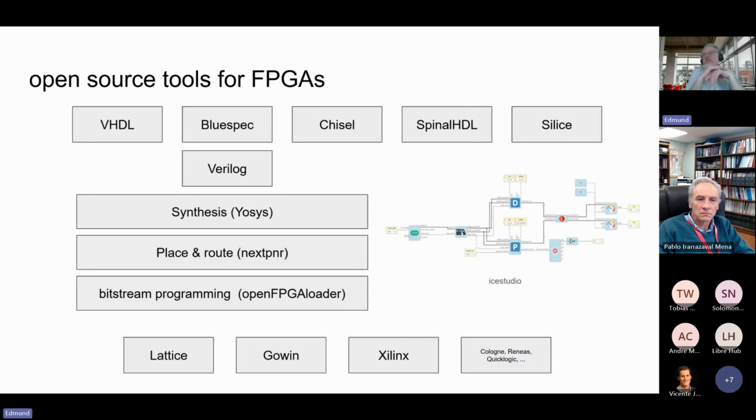Since 8 years, there is also the tool called Icestudio, which is a graphical design interface with the intention to teach 10 to 15-year-old children to program FPGAs. So you can put your elements like pins, like buttons into the user interface and wire them up, and then generate the bit stream and make the board do whatever you wanted it to do. It also has the possibility to include a block where you write Verilog directly into it. So it's a rather flexible, but also an easy solution.